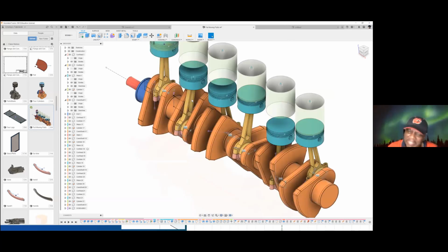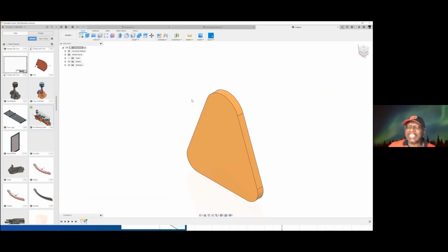One thing you notice is that after you have created that thing, the sketch goes off. But we are not finished. We are not done with that sketch yet. So we can go back and turn that sketch back on. You go to the sketches here, pick it, and turn the sketch on, so you can see the sketch reappears. What I want to do next is to do an extrusion.